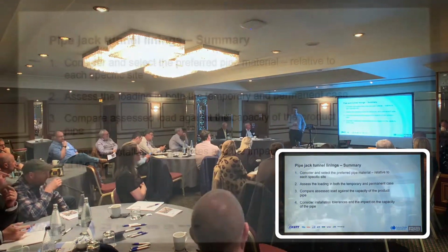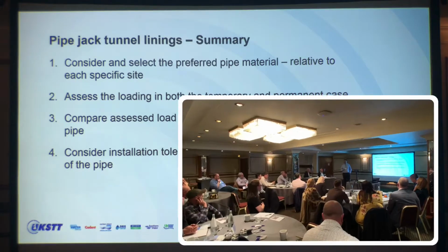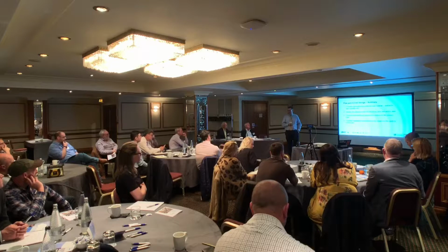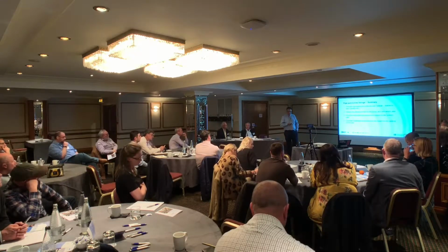Maybe pick the phone up to a pipe jacking contractor, or hopefully you might have your contractor appointed, and ask them, what do you think about this? What tolerance do you think you can hit? Do you think you'll get any misalignment? Hopefully they're an honest enough crowd to say, this is typically what we get, or they might be able to give you some data to prove the tolerances that they've achieved in the past.